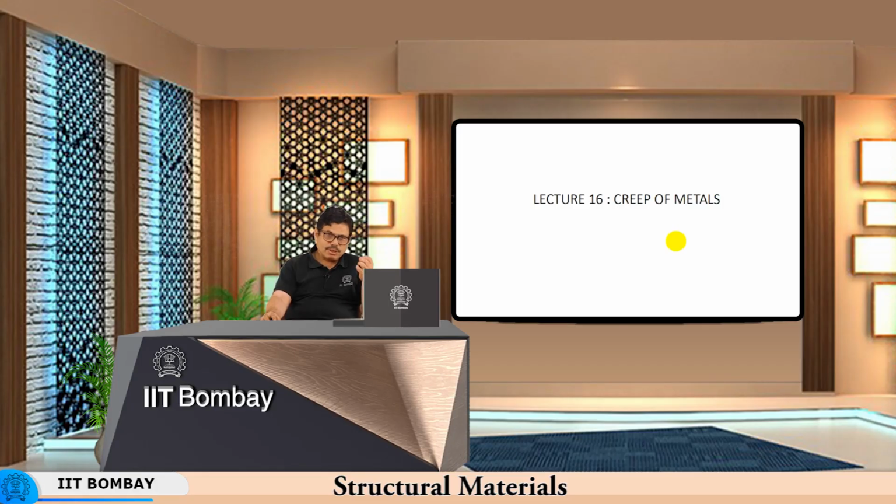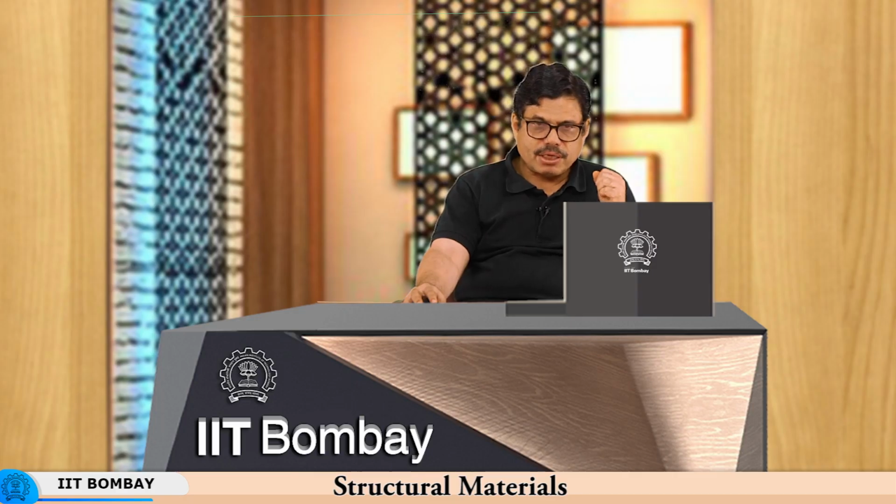So, in case of steel, it could turn into either pearlite or bainite or martensite depending on the cooling rate. Now, when we talk about heating the material and maintaining it at high temperatures for a prolonged period of time in service, the picture is completely different. That is because the material not only undergoes microstructural changes, but it also results in different rates of deformation.